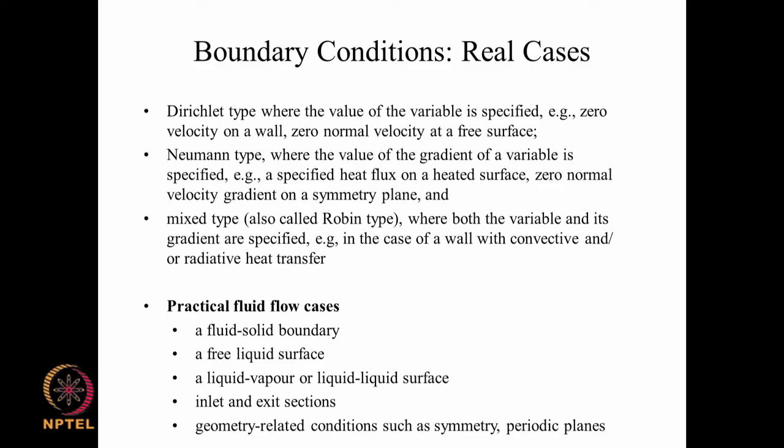In such a case, on the outside of the computational domain you have, for example, natural convection, which means there is a heat transfer coefficient that may be of the order of 5 to 10 watts per meter square degree centigrade, with which heat is evacuated from the surface, and how much heat flux it is depends on the temperature difference between the wall and the ambient.